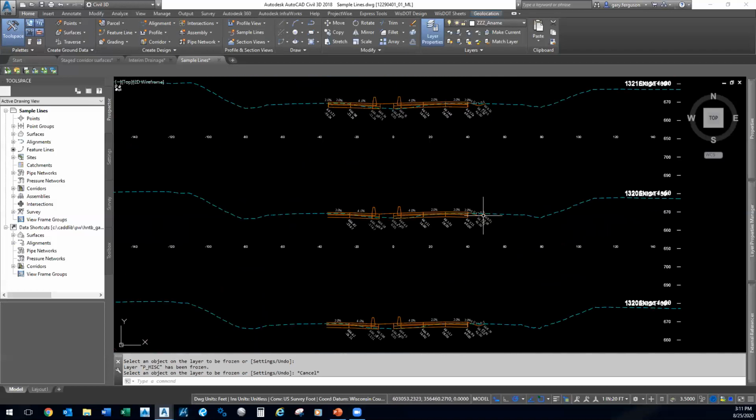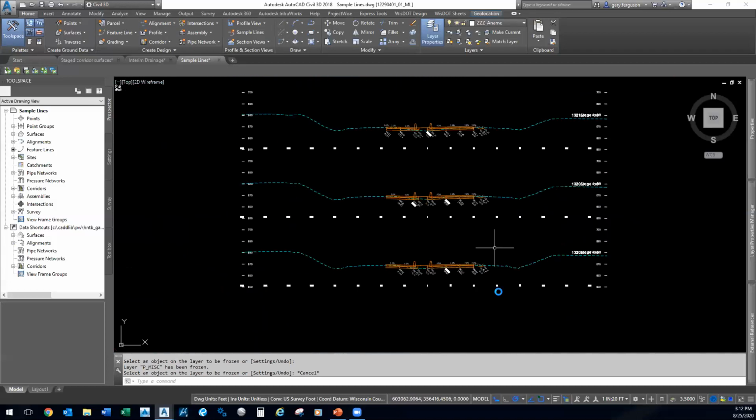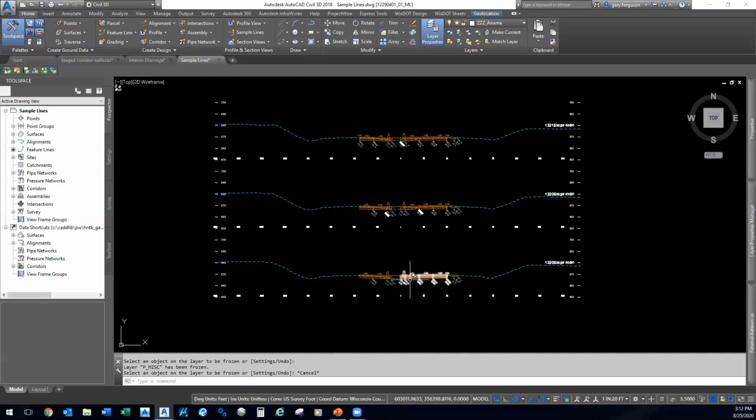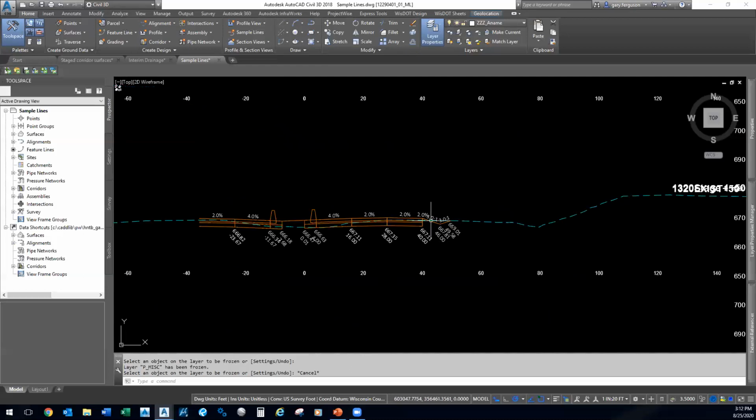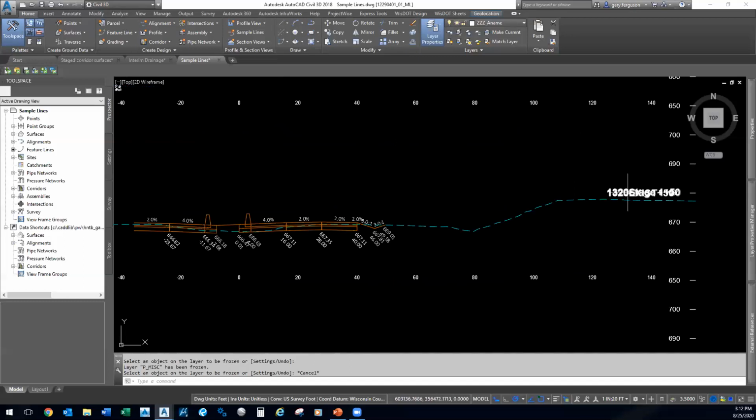And now what this gives us is the ability to label these sections not as northbound or southbound, but this is stage 1 of mainline. And it represents exactly what the contractor has to build in stage 1. And we have a surface to pair with that top and datum. So now we're providing them all of the information and all of the tools to easily build partial width with interim drainage considerations. Now you can see over here, some of this text is overlapping.